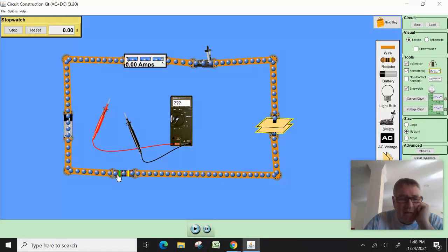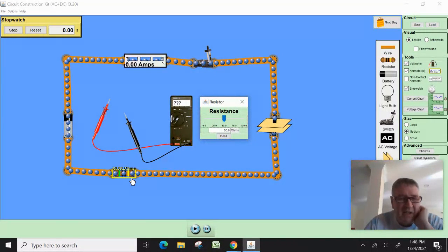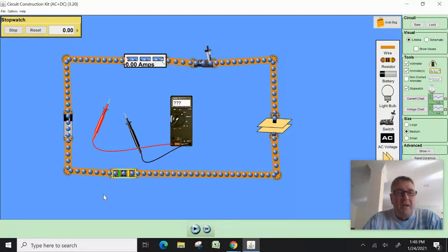And then down here we have a resistor, and resistors we use to dissipate the energy in the capacitor. Let me look at that value. The RC value is also going to set the time constant, how quickly or how slowly it charges and discharges. So this is really looking at the charging curve. Now, at the top of your lab sheet, you'll see this RC constant. We did this in the other lab. We didn't actually do the lab, but I showed you what you would have done. I built the circuit and showed you. In that lab, I picked a particular R value and a particular C value and got an RC constant. We saw how long it took to charge and discharge that capacitor circuit. In this case, R times C equals 10.